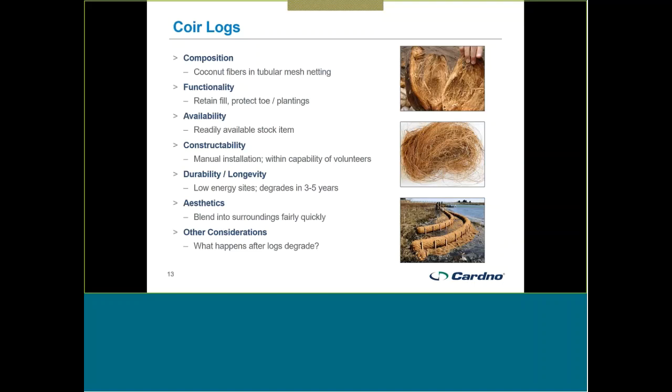So I think one of the key considerations for biologs, they have their place, but it's very important to think about what's going to happen to my shoreline, what's going to happen to the functionality of my design in 3 to 5 years when these Coir Logs have biodegraded. Will I have lost an integral component of my design, or are they really only intended to help stabilize the site in those critical first few years while other components, primarily vegetation, are getting established, and by the time the biolog has degraded, the vegetation will be mature enough that it can stabilize the shoreline.